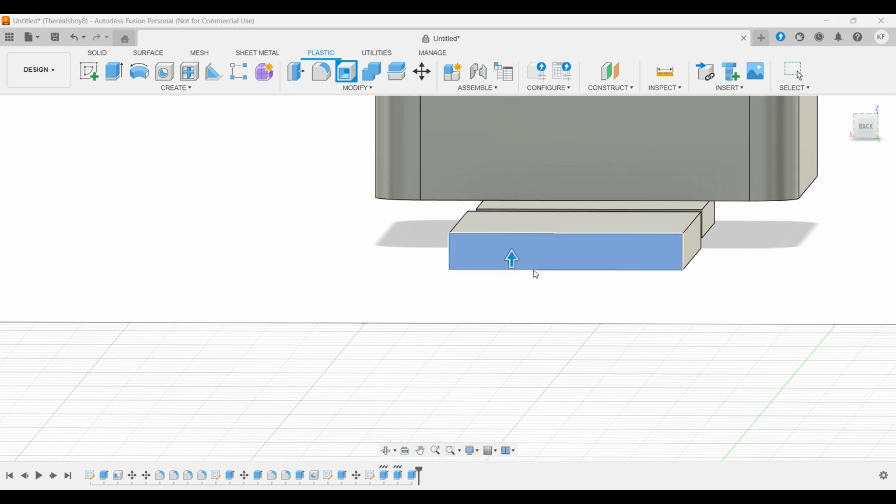Again, we are going to put a shell in the inside. And the inside thickness, we'll put it as 2. But sometimes objects are too small for you to be able to do that. So if you can do something like 1, that'll be all right. Maybe we might even be able to do 0.5. See? Now that we have this little thing inside,